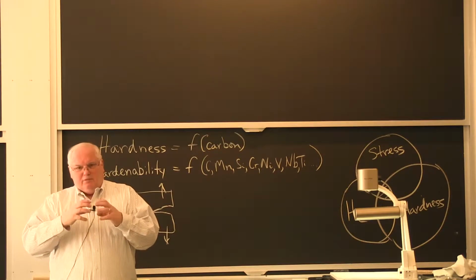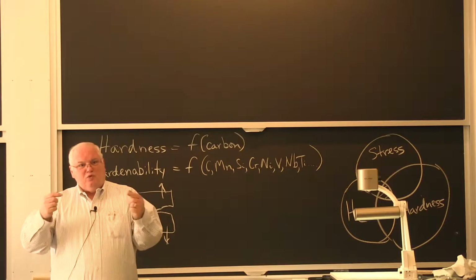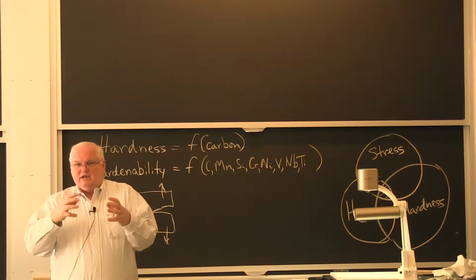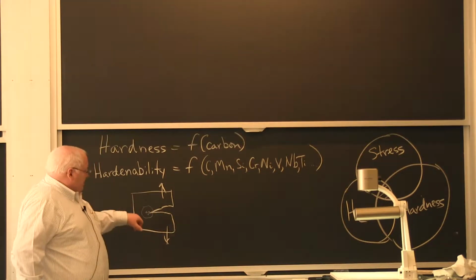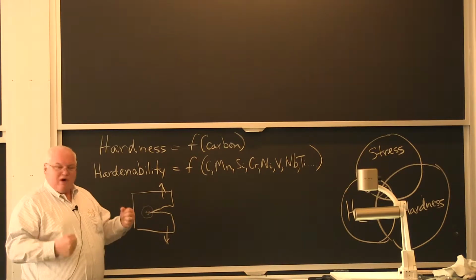Well, hydrogen is an interstitial atom. It likes to strain the lattice. And if you strain the lattice, the hydrogen will go to the lowest energy state where the lattice is already expanded. That's at the cracked tip, okay? I'm pulling on the lattice at the cracked tip.